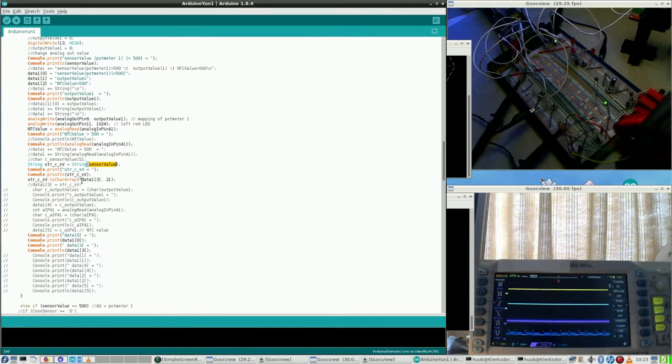Sensor value is going to cell 3 of this one, and there it goes. Let's see if it changes a bit. Yep, it changes. So whenever this rubber is blocking the light, you can see that it is dropping, but it is now on 200 millivolts, 0.2 of a volt, and only then you can see it.